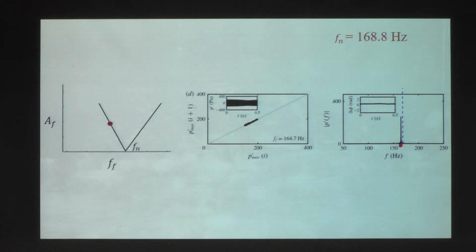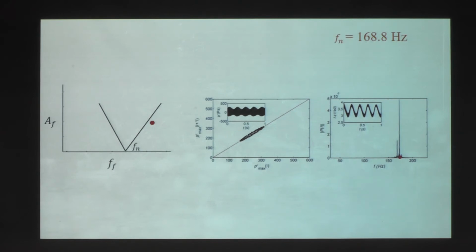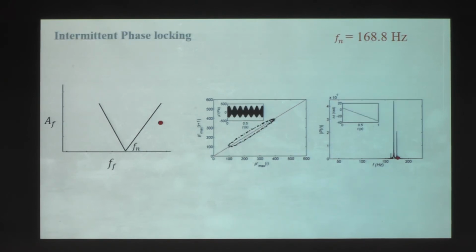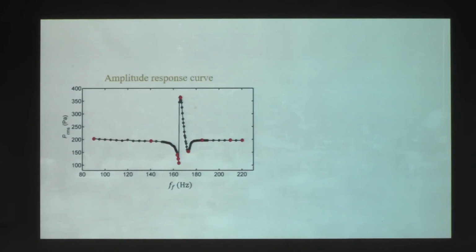So these are the dynamics we can have. If you go further inside the regime, again it is locked, there is only one frequency signal, completely periodic. If you go further, you go through phase trapping again, that is bounded relative phase, then intermittent locking, and then phase drifting. So these are the dynamics we are going to get.